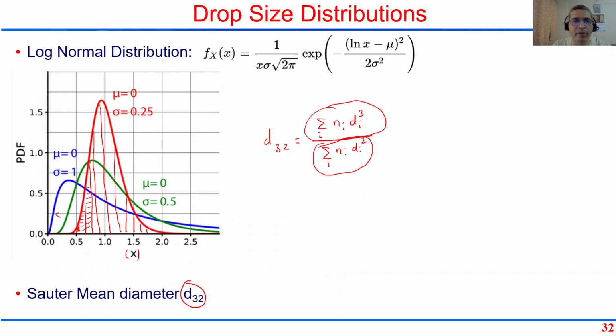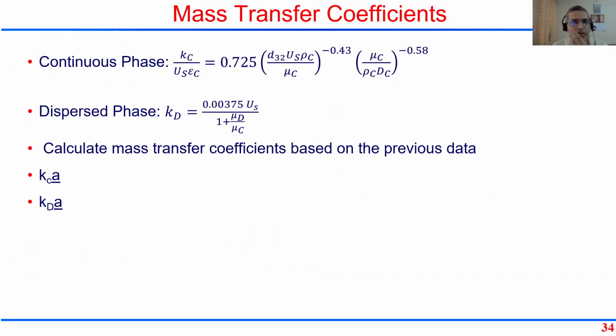So again, people have done experiments and made some empirical correlations for mass transfer coefficients. So I'm just going to give you two such empirical correlations. There are several that people have proposed. So this is like your Reynolds number, droplet based Reynolds number, okay, and this is like your Schmidt number. Normally you would want a Sherwood number here. So this is like a Sherwood number, but it is not the usual kind of Sherwood number. Some more things are there in this.